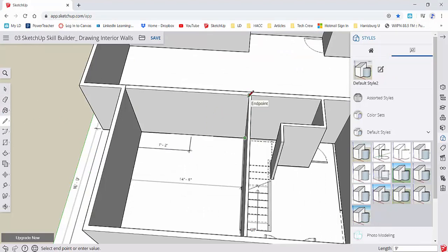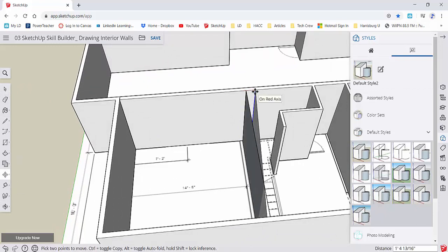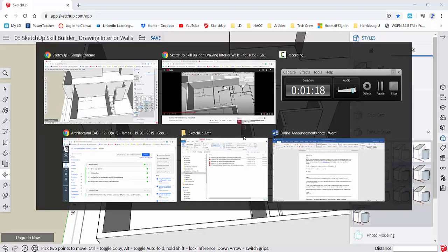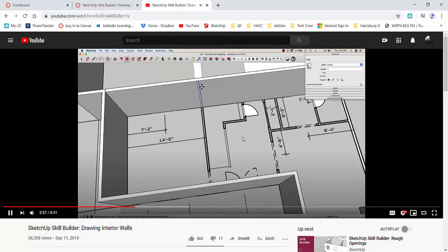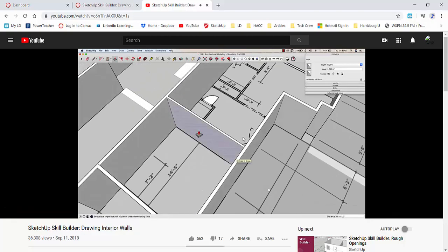You went up on the blue, and then you click on your selection tool, click on the line that you made, the move tool, and you move it over. As you're moving it over, you hit Control, and it makes a copy. Then you type in your distance, 5.5 inches, and enter. And then I can use, again, push-pull to just drag that to the other side.